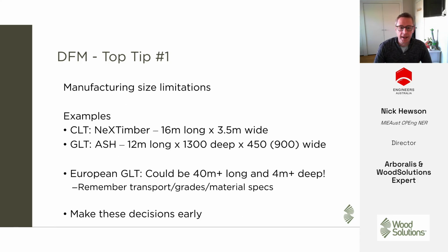So we need to take into account individual manufacturers' capability. So how long, how wide, what sort of sizes they can make the elements, whether this is a locally sourced project from Australia or whether it's from Europe. Need to make these decisions early in the process, because these can lock in a lot of decisions around structural grids that become very, very important later on.